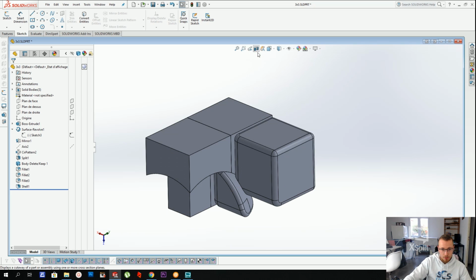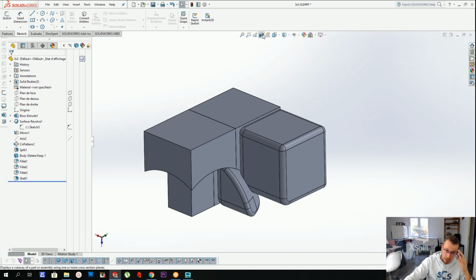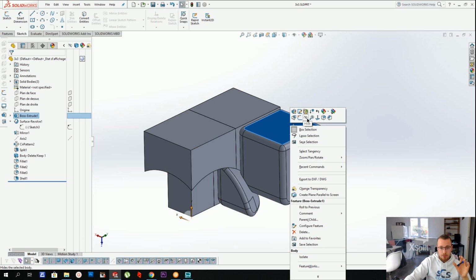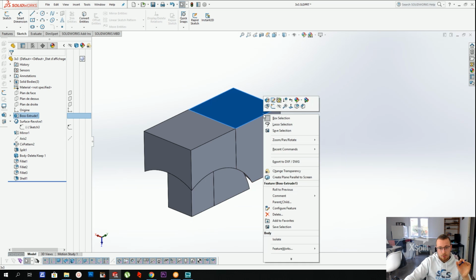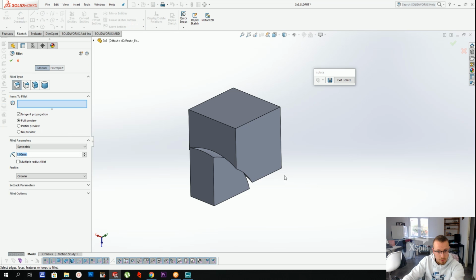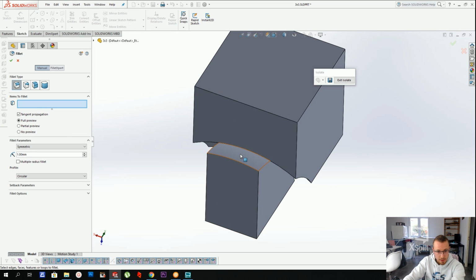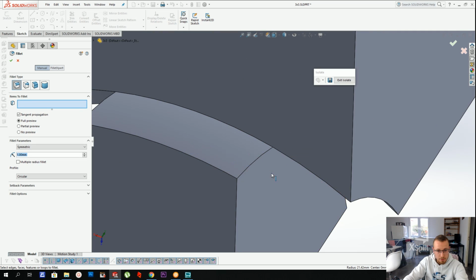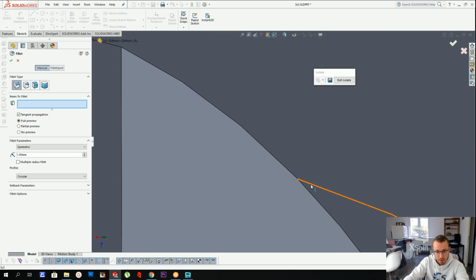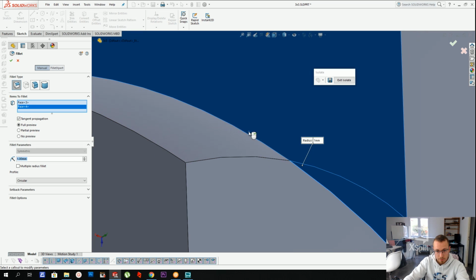Okay, so let's undo that section view that I did. By the way, here's the section view icon. I hope I'm not going too fast. But now this part is done, completely done. So now what we're going to do is tweak the edge, prepare the edge for 3D printing. Now here's something very interesting. You can't just select that face because it has trouble identifying, like when you have two edges that intersect on the same surface, but one is like on the negative and one is on the positive on top.